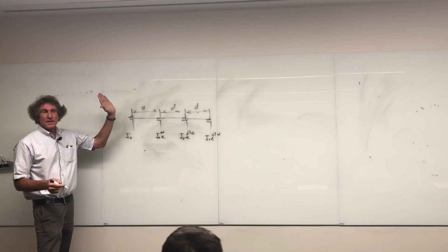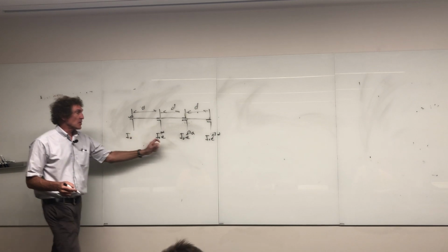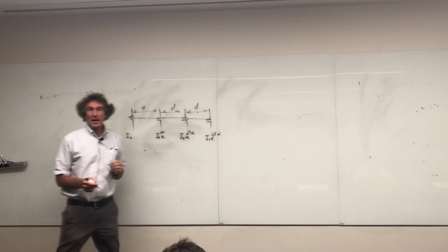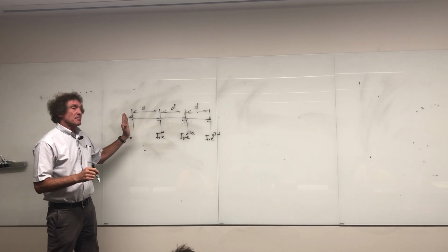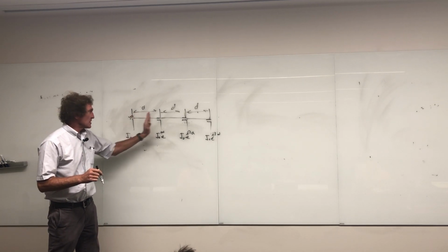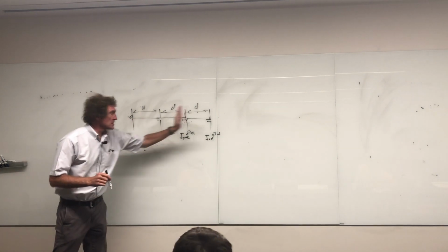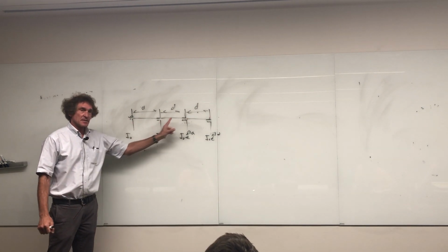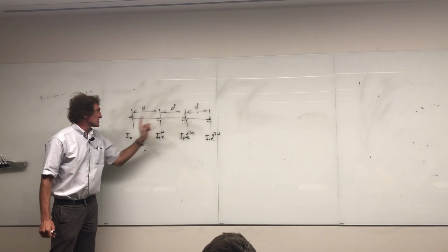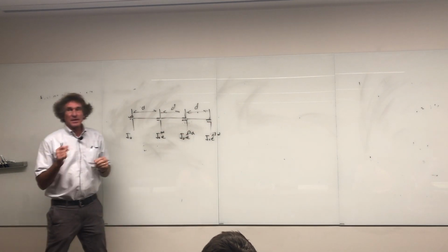Now, I want to tell you this. To get these currents is no small thing. Here's why. It's not the phase, it's the magnitude. There's an impedance interaction between this one and this one, this one and this one, and this one and this one. It means the driving point impedance of this element is different from this one, is different from this. Well, these two will be the same, and these two will be the same. But the impedance is different.